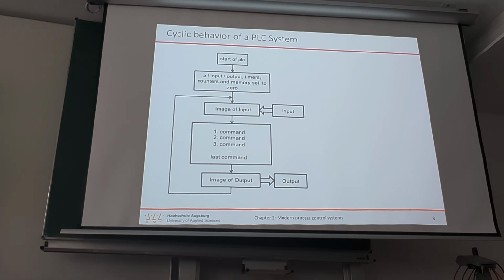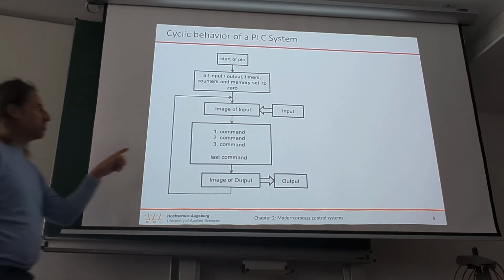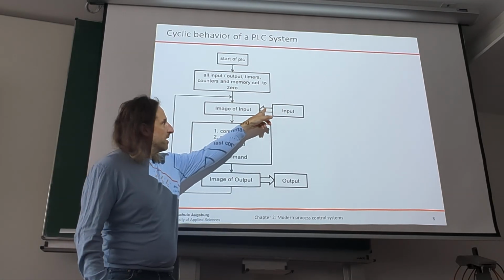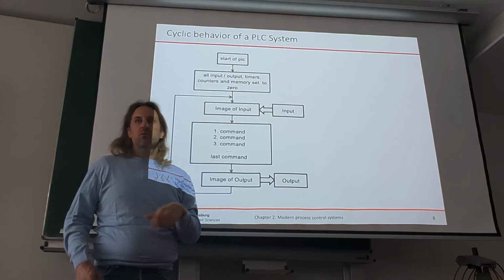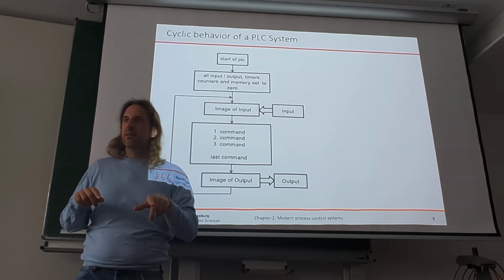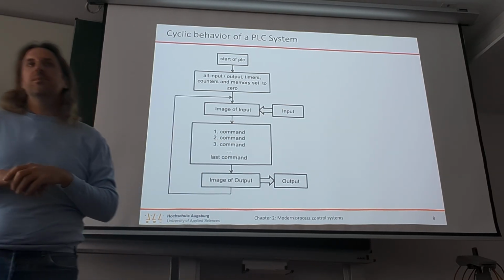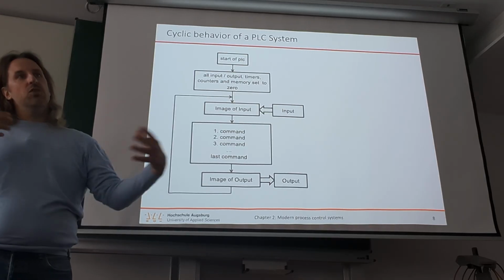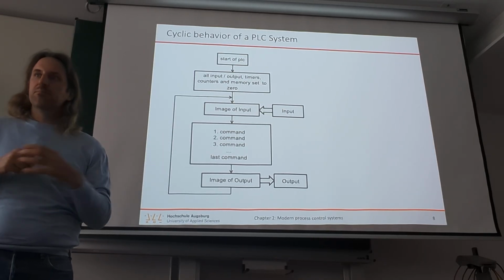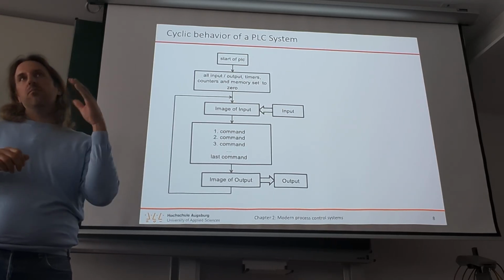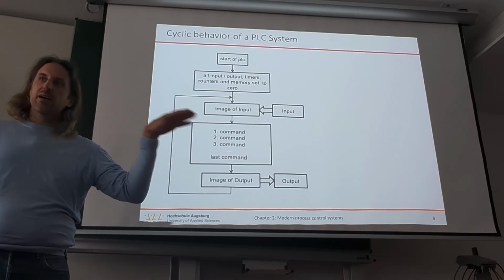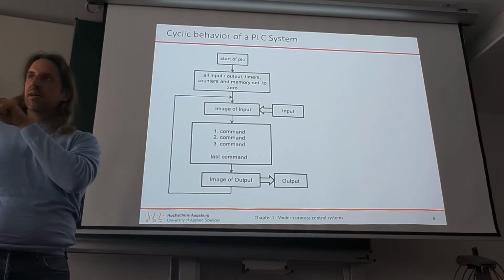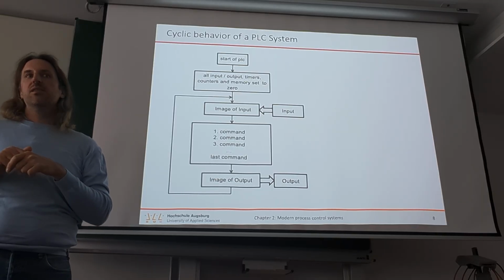So what they actually do is, this process is way more complex. Usually the automation system sends out a clock to all the I/O components and synchronizes the time. And then it says the next cycle begins at that timestamp, and then all the IOs sample their IO information at that timestamp.